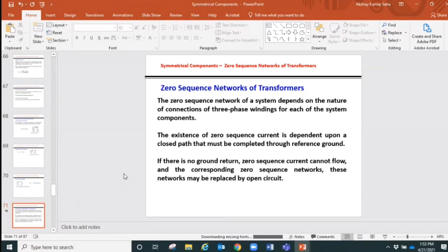So when they do the load shedding, they actually switch off. The secondary side is open. Also, you may want to do it for the primary for the purpose of protecting. If you want to take the opportunity to do some maintenance during that load shedding time, we also do that kind of activity. Like, I know that there will be a load shed for 2 hours, and I knew that the transformer was having some trouble, so let's take that opportunity to do some maintenance in the 2 hours and fix that. So the point is that we can leave the secondary open, and we also can apply loads as we need or as we would want.